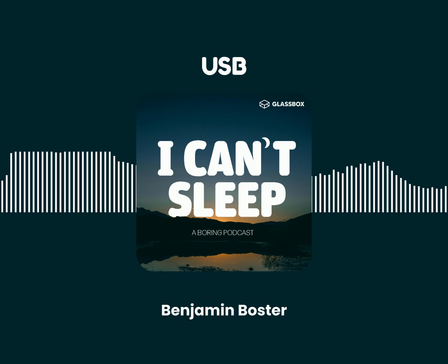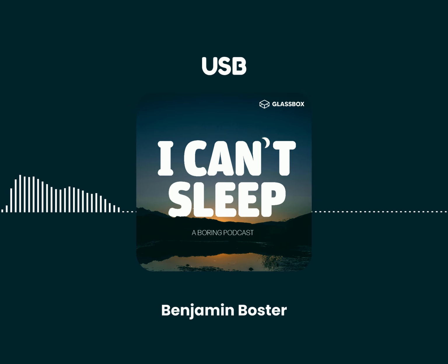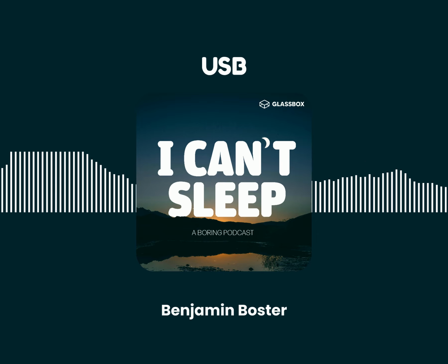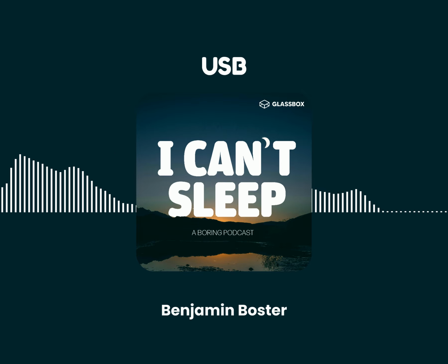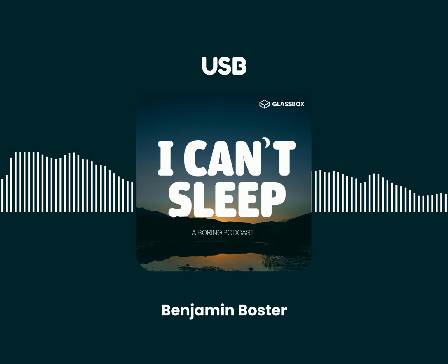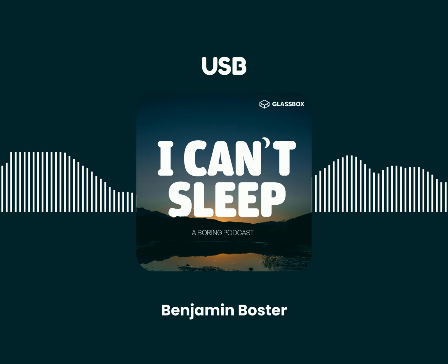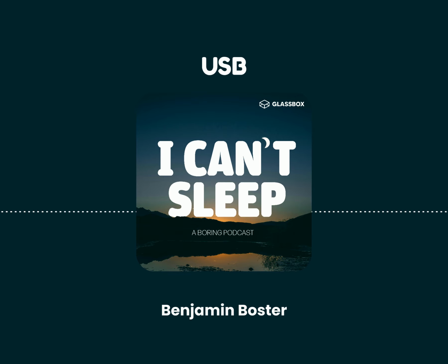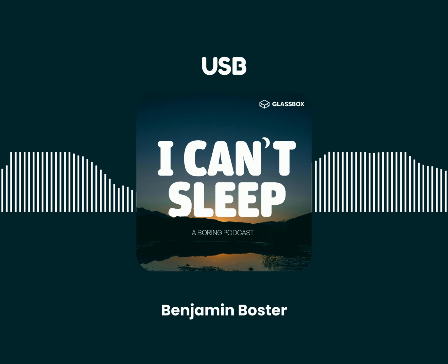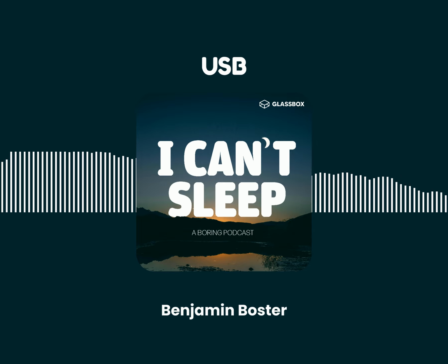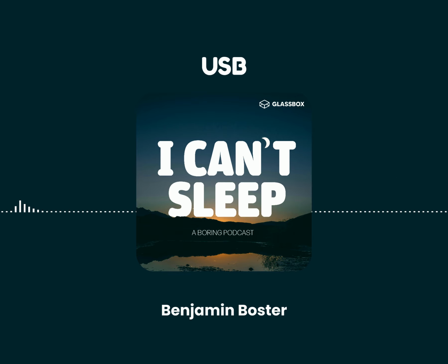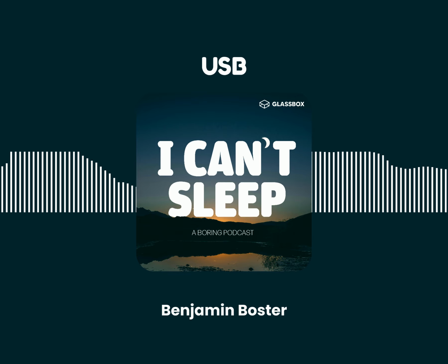USB also provides power to peripheral devices. The latest versions of the standard extend the power delivery limits for battery charging and devices requiring up to 240 watts, USB Power Delivery, USB PD. Over the years, USB PD has been adopted as the standard power supply and charging format for many mobile devices, such as mobile phones, reducing the need for proprietary chargers.